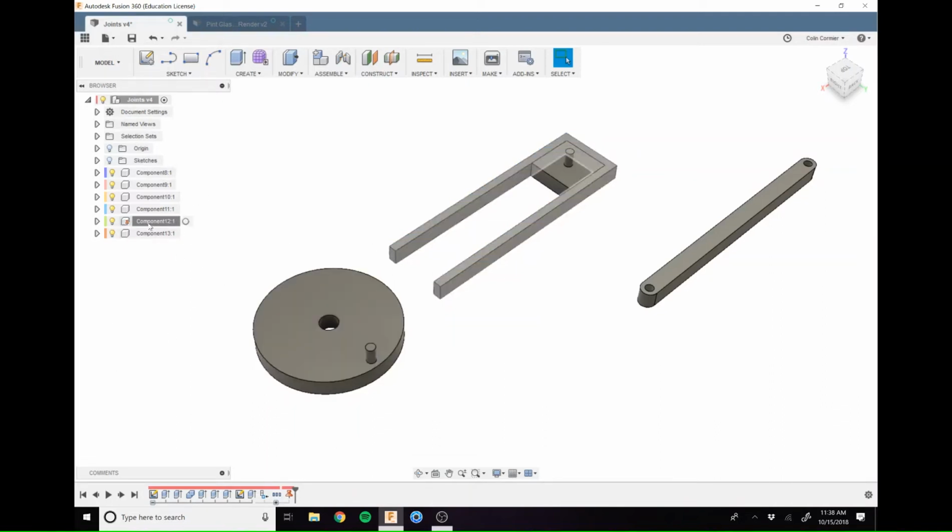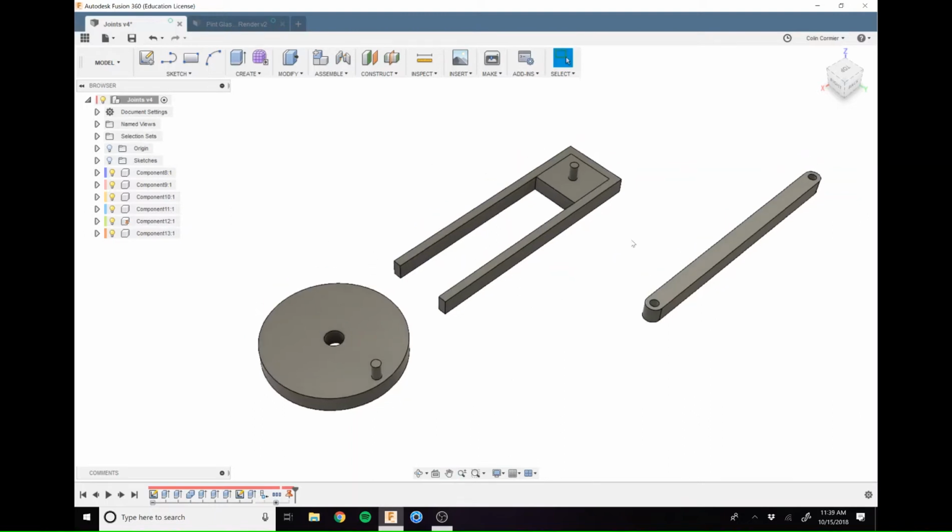I've seen a lot of students so far go through their whole toy assembly, create really complicated joints with really complicated mechanisms. They go to animate it and it just explodes and Fusion can't figure it out. It's because they don't have a grounded component. Essentially, they'll go to move or animate one component and everything just starts flying around the place because there's no grounded reference for how stuff moves. So just be aware that you usually want at least one grounded component. And it's somewhat situational, depending on the joints that you have, you may have a couple other grounded components.